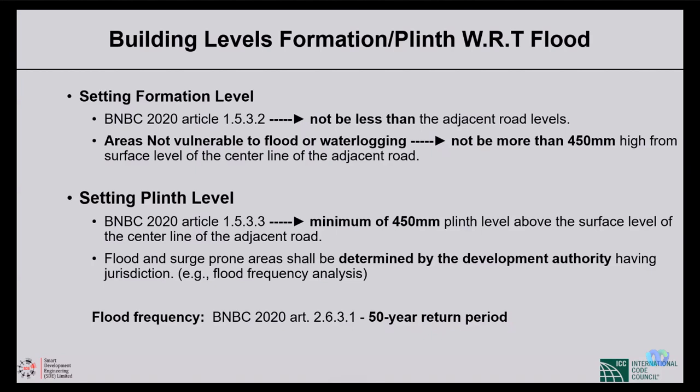Beside, also mentioned are areas not flood vulnerable or drainage problem areas. If not, that area also mentions not more than 450. Don't put your plinth level so high, more than 450 millimeters from the road level. That's also mentioned.